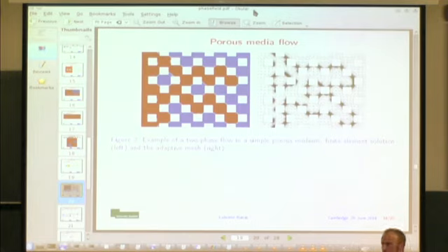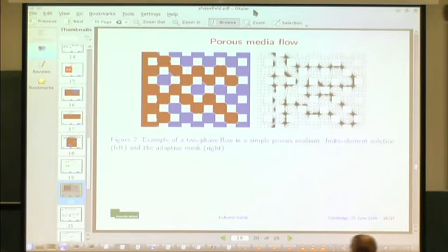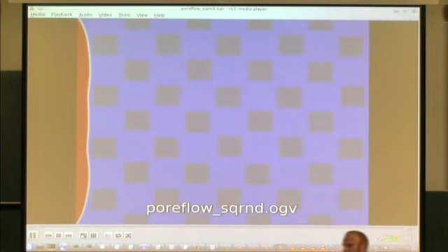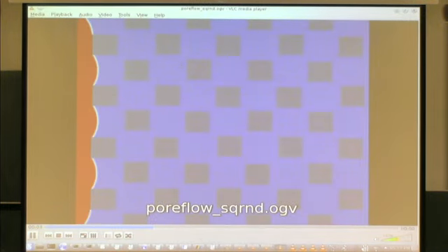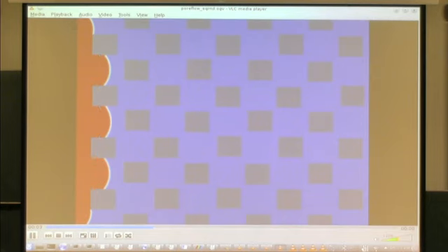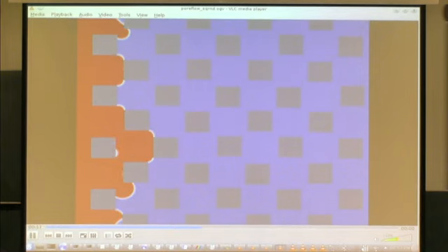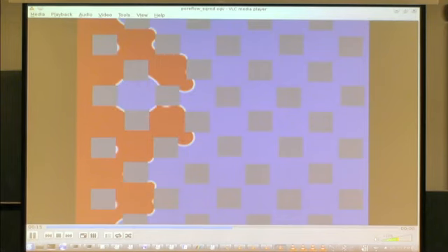We were also interested in porous media flow, where all these surface tension and contact angle effects play an important role. And I will show you the following video of the so-called fingering. If there is a strong surface tension and under a certain contact angle condition, the flow via the porous medium, so these are square pores with some random perturbation, the fluid will find some preferential paths and will form so-called fingers.